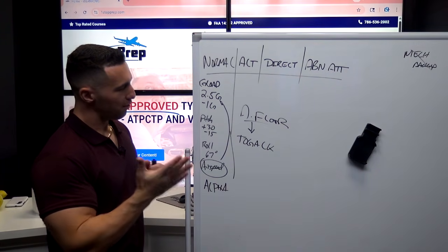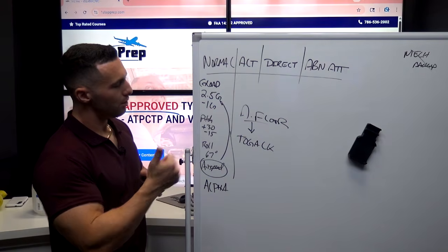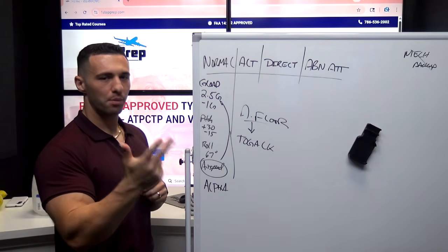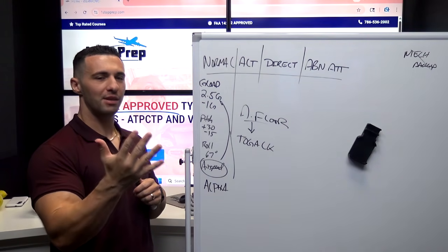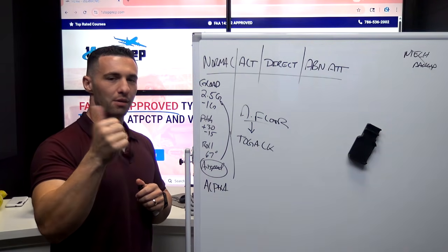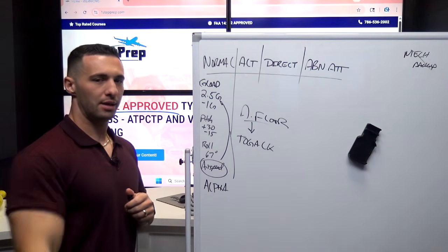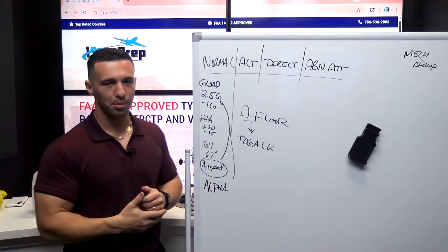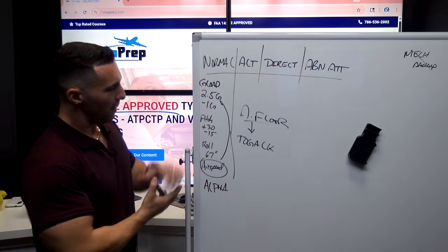So in total, remember there's 5 when we talk about normal law: G-load protection, roll, pitch, speed, alphas. The alphas have 3: max, floor, and prot. We talked first about prot, then max, and floor. And that's all in normal law.